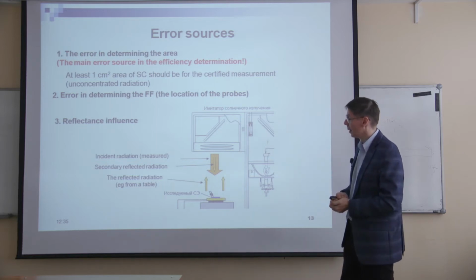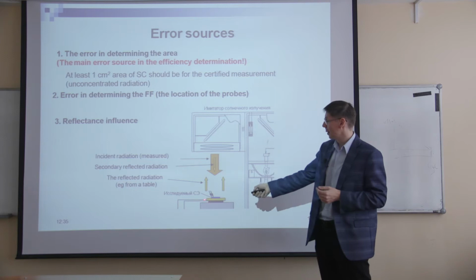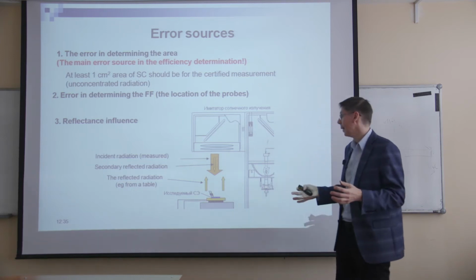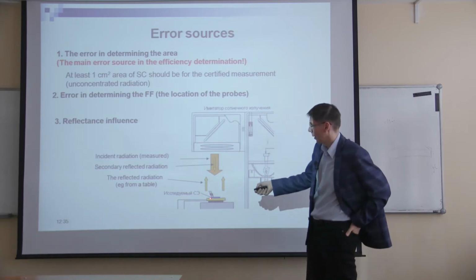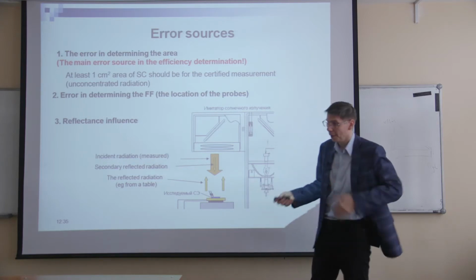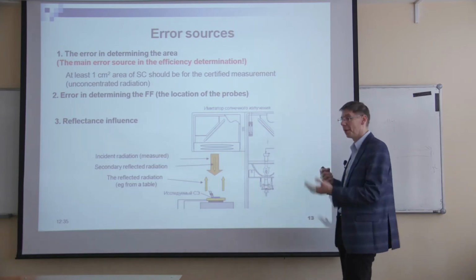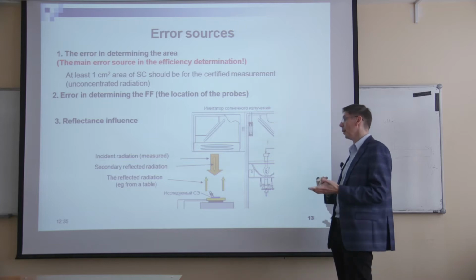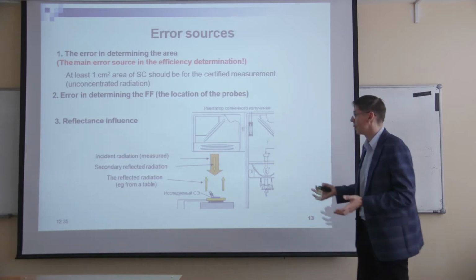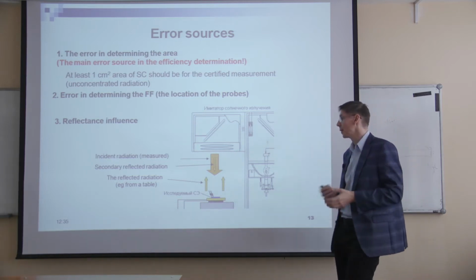But the problem is that if you illuminate this cell, you would generate carriers in the whole wafer, and the charge carriers which are generated within the diffusion length would participate in the current also. And this diffusion length for solar cells of high efficiency would be quite large. It's up to a few millimeters, or even up to centimeters. It's crazy, but up to centimeters.